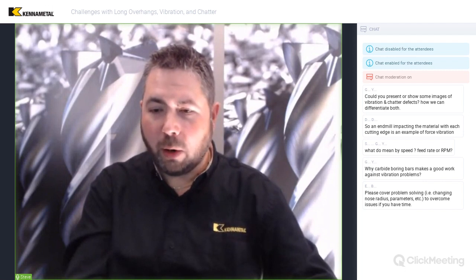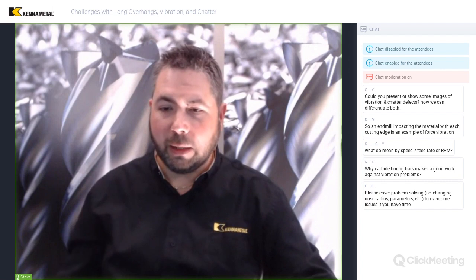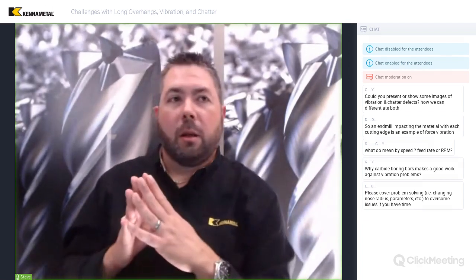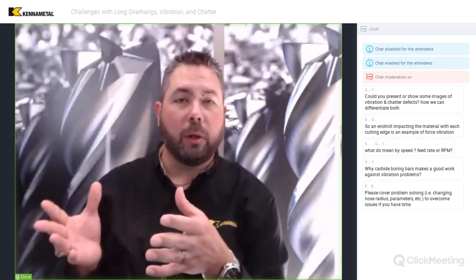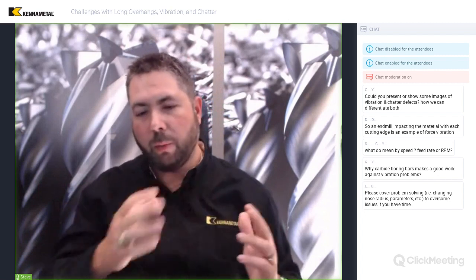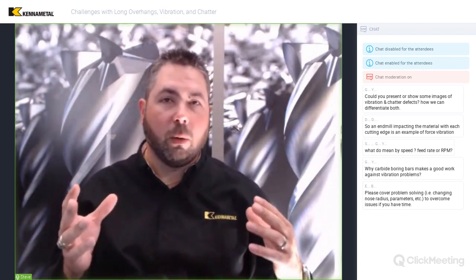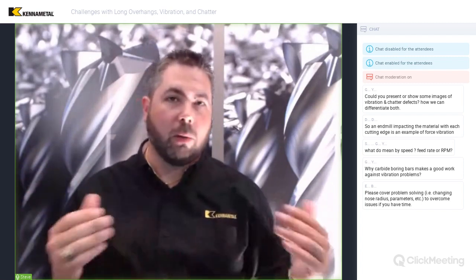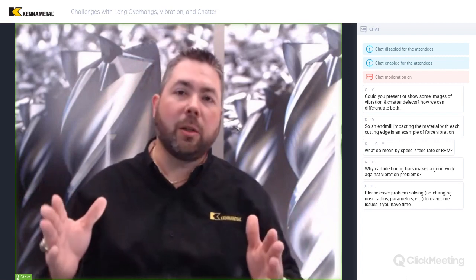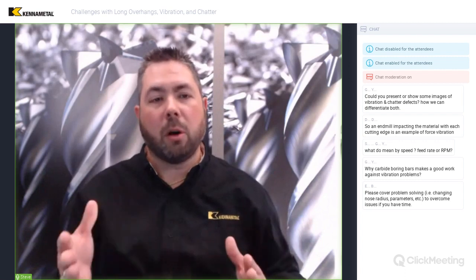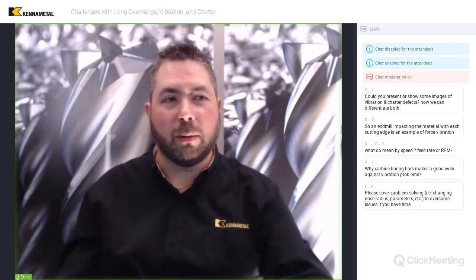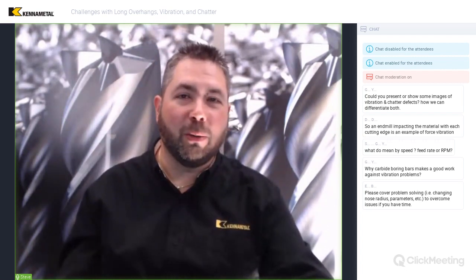Somebody was asking why carbide boring bars help against vibration problems. That's a good question, and we talked about that a little bit in the beginning. What the carbide boring bar does is it increases the stiffness. We have essentially two ways that we can tackle this vibration problem, well, more than two, but fundamentally in terms of the bar design, we can make the bar stiffer and stiffer. That's essentially what the carbide is doing. But eventually, even with carbide, we're going to get to a length where it's still not going to be completely stable. So carbide is going to be better than steel, but once we exceed what carbide can do, that's where the vibration-free bars come into play. In that case, we're able to use a little bit of science and engineering to offset that vibration.